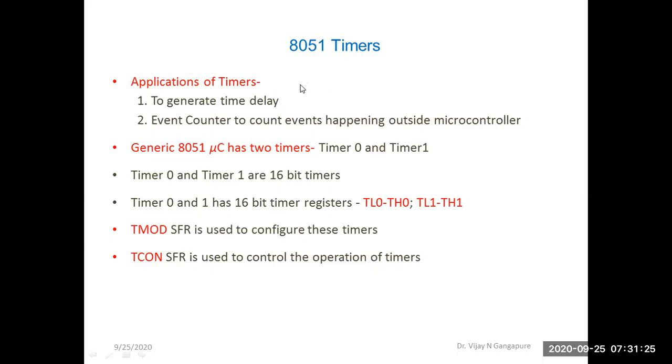Similarly here also you can start a timer and the timer will start counting up. The only difference is that when you use 8051 timers, you can start counting from initial values set by you. That is the only difference.